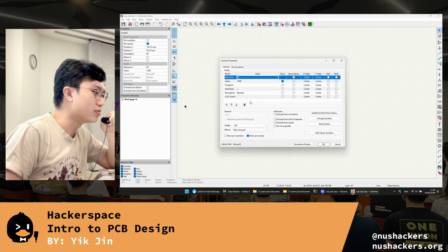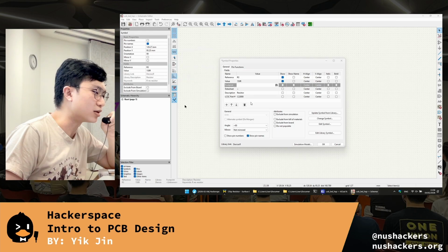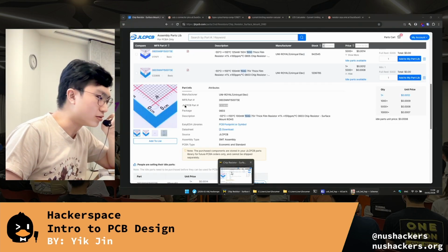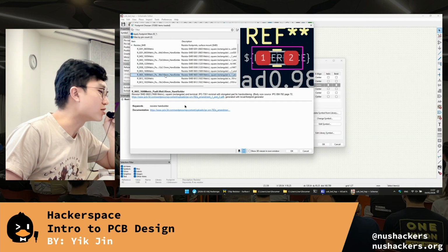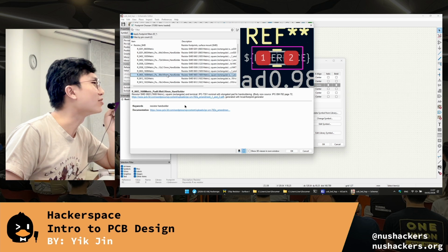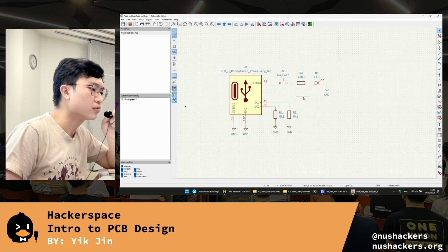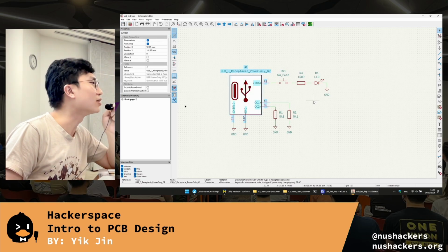So I do the same thing, nothing new. This is now 0603. So it's no longer 0402, it's 0603. So I choose this, the hand solder version. Can, right? This should be pretty familiar to you already because it's just literally repeating the same things for all the parts. So save it. One last part that we haven't chosen is this USB receptacle, right?